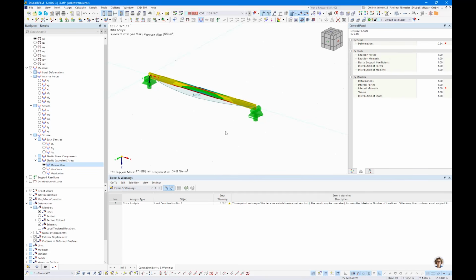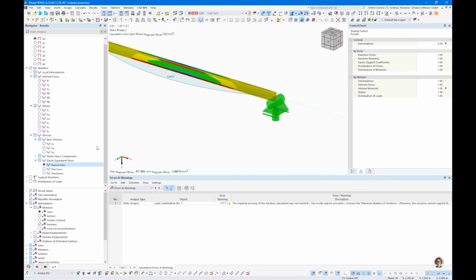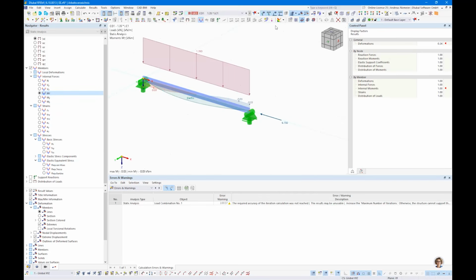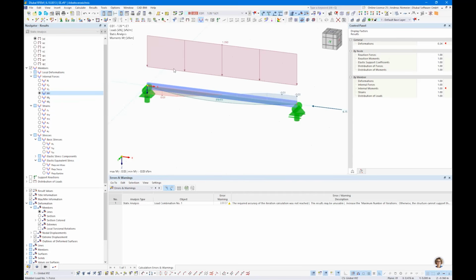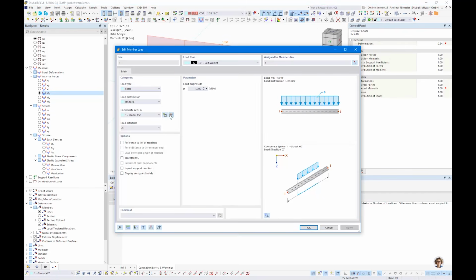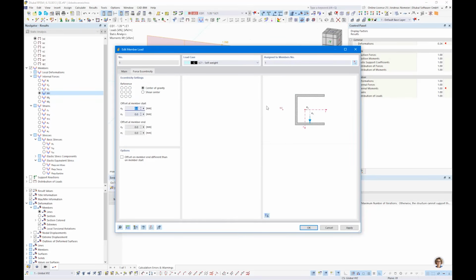And the point is, yes, you have to do something more because you have a torsional moment. This brings me to the situation we should clarify at which place the load is acting. So at the moment the load is acting in the center of shear, what means it's behind. But I place it now in reality here on this beam.